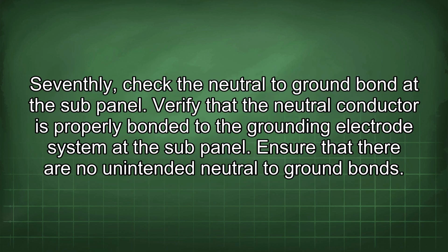Seventhly, check the neutral to ground bond at the subpanel. Verify that the neutral conductor is properly bonded to the grounding electrode system at the subpanel. Ensure that there are no unintended neutral to ground bonds.